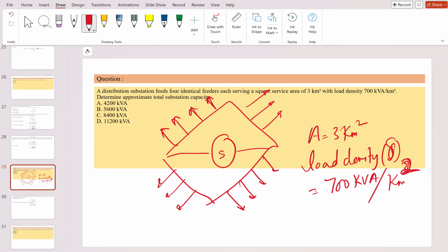This is another type of question. If you know the formula, just fit it in and get the answer. Otherwise, I will give the formula directly. You just have to remember it; see the slide, what is already given. Write it column wise: uniformly distributed and non-uniformly distributed. For a triangular shaped feeder or hexagon, write the power loss and voltage drop formulas. That is most important, the formula, and remembering which is uniform and which is non-uniform. I will add that to my slide and upload it. But from your side, this kind of problem will come.